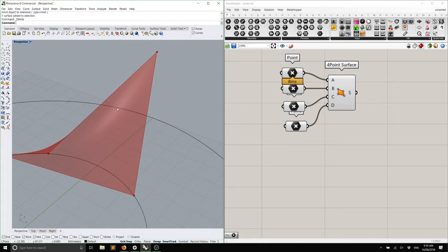No? It's basically generating 2 triangles, yeah? Because it really can't achieve double curvature in that surface, because for this to actually create a hyperbolic paraboloid, it needs to be able to stretch or shrink, and paper doesn't want to stretch or shrink, okay?